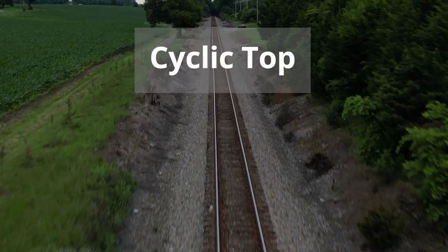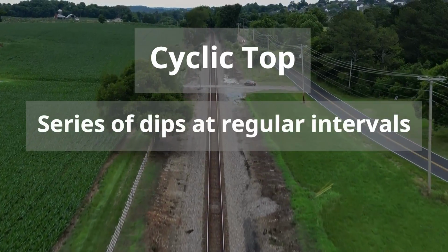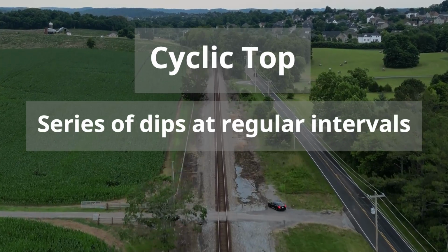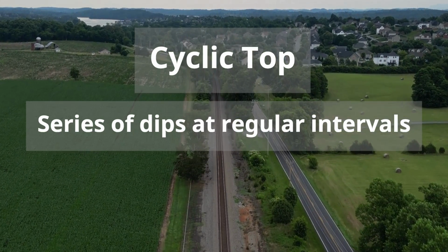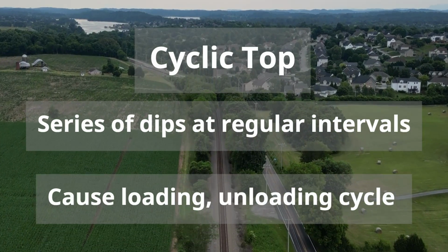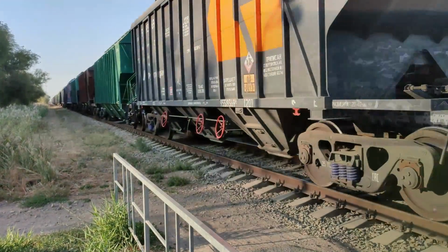Cyclic top. Cyclic top is a series of dips in a route, looking like a wave. They are a problem for trains, particularly freight with its stiff suspension. They cause a cycle of loading and unloading of the suspension. This buildup of energy can cause trains to eventually jump off the rail head.